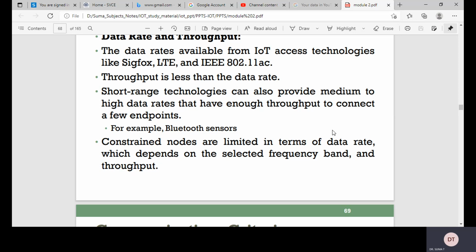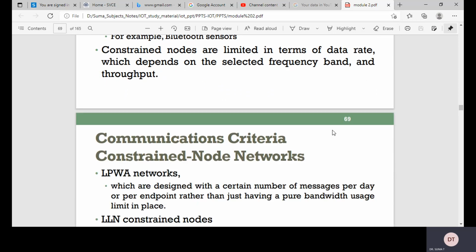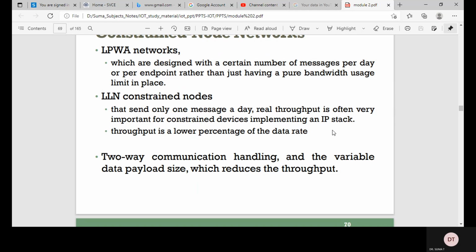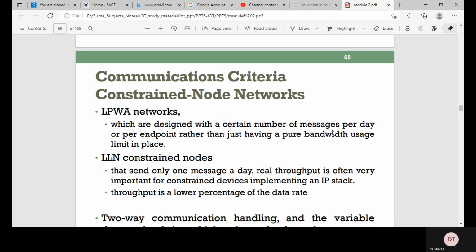given time. If you take the example of IEEE 802.15.4G, in the border case of distance and radio signal quality, the FEC will be turned on, which lowers the data rate from 150 kbps to 75 kbps.